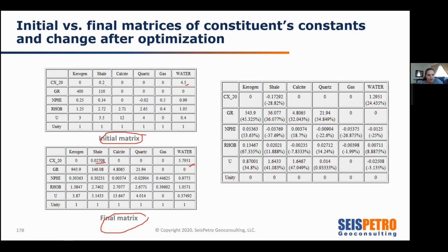So we see that you changed the calcite to almost 2.71, that is reasonable. The quartz is heavy, at 2.67. Well, that actually is still reasonable if you have pyrite in the system, but you need to know that you have pyrite, because if you don't, then 2.67 for quartz doesn't make sense, and you have to lower the maximum limit on your constant.